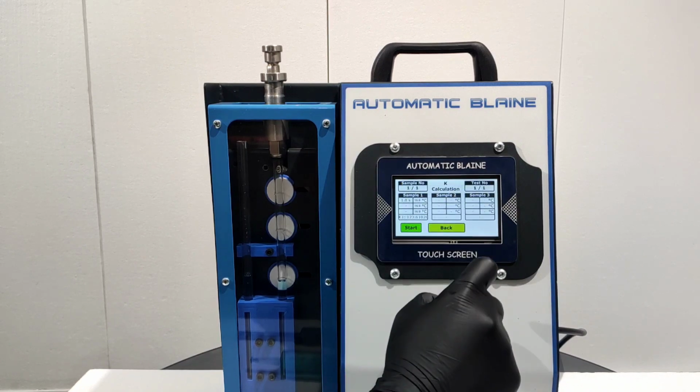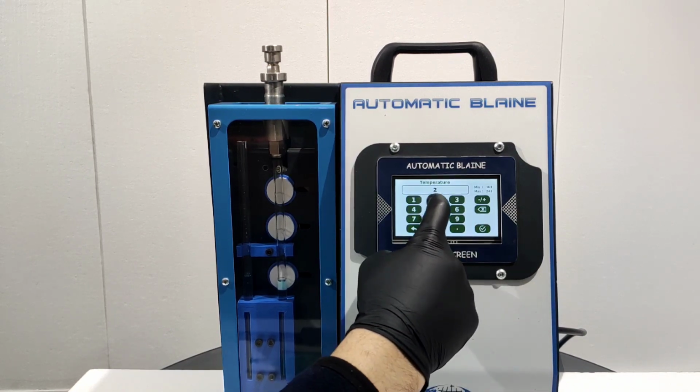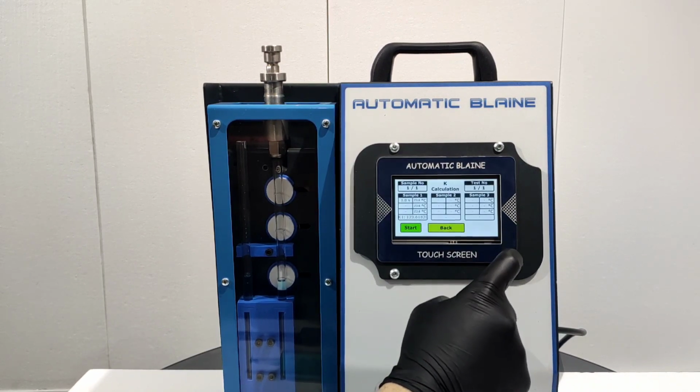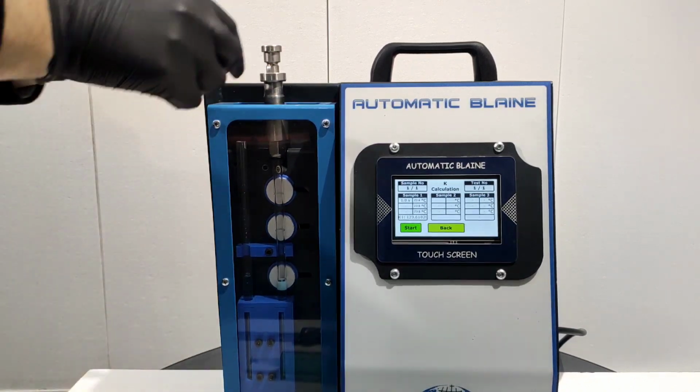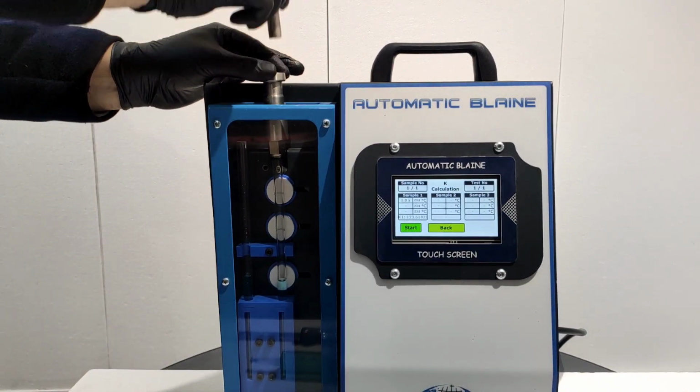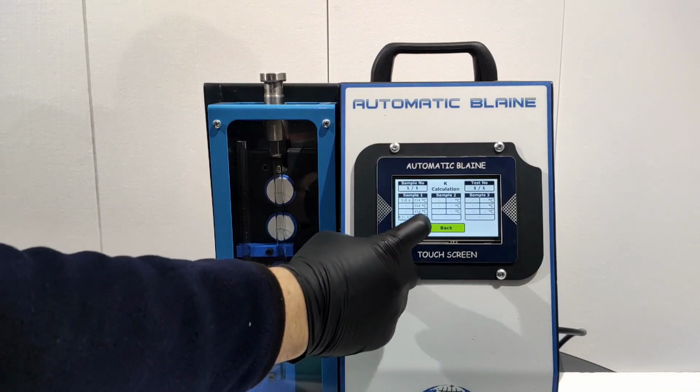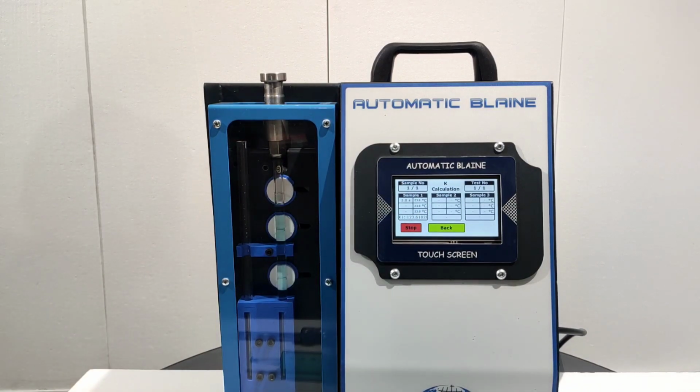Press the start button. Measure the ambient temperature. Use this measured temperature value in your calculation. The pump draws the liquid above the highest level and stops at the highest level. Then, as time passes, the liquid level in the U-tube drops. The time starts when the liquid goes down to the second level. After passing the lowest level, the measured time is displayed.